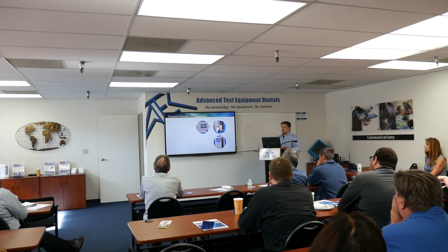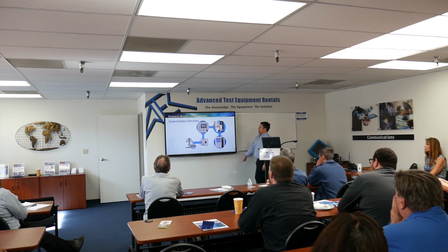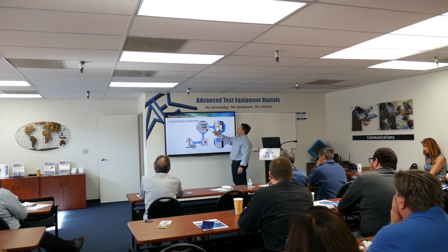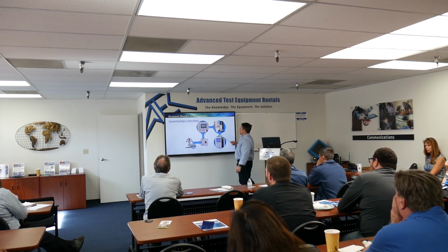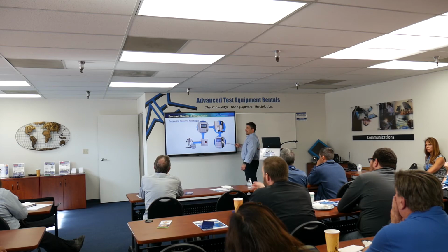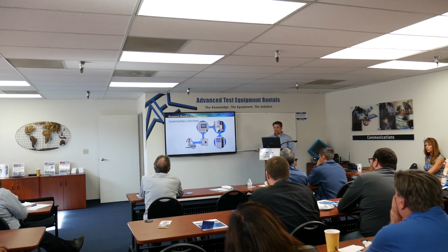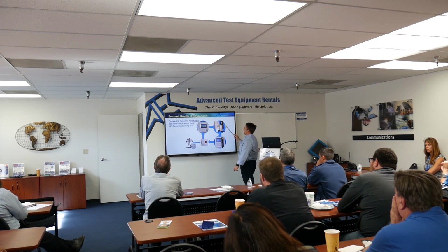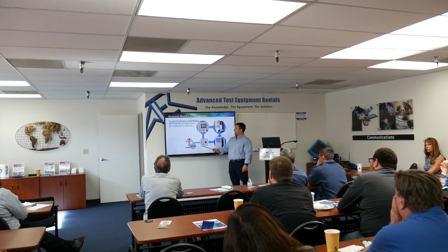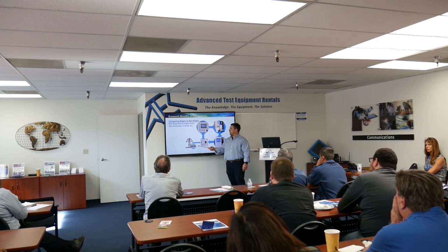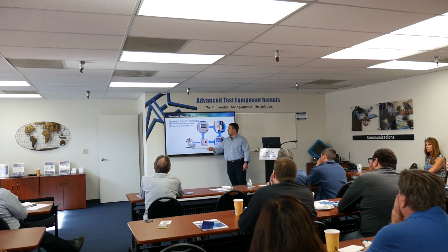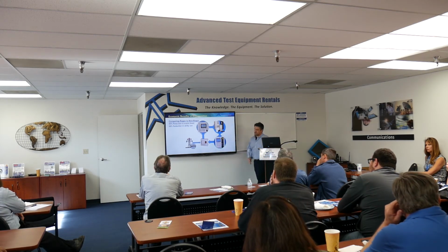And then you have our loads here. For the traditional non-regenerative, where power just goes one way, you can see it follows around here. Your AC comes in, you have your source, powers your equipment, goes to your load, and burns off here, and that's it. But with regen, instead of burning off your power, you're actually putting it back onto the grid. So what the grid power company is seeing is really just the net loss of the system.